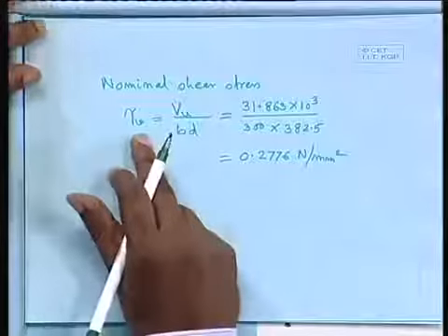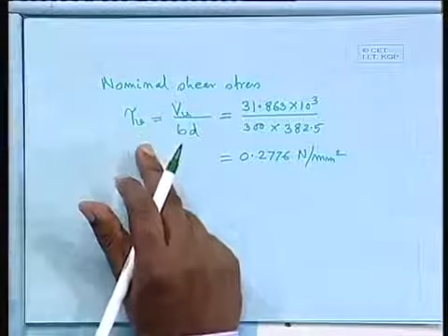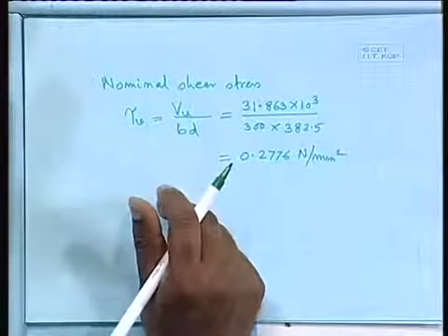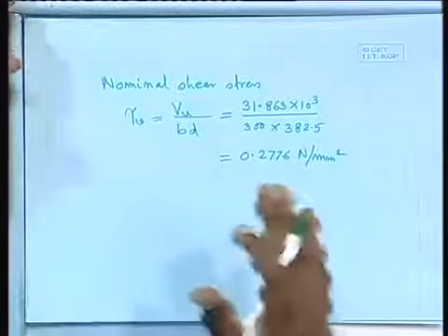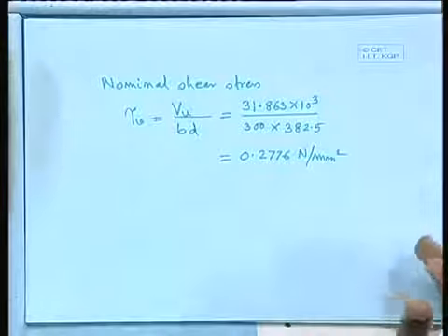That tau V is not simply the shear force, so we have to modify it due to the varying depth, and then we can do our calculation. That means tau V and then tau C, all those things, then again we can continue whatever we have done in the last class. So this is the one we shall do to find out the nominal shear stress.